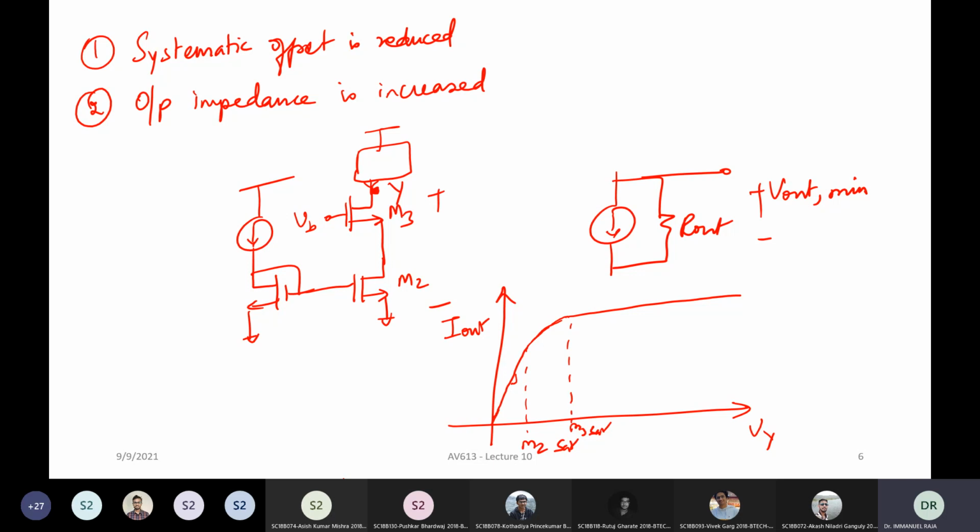And then you have your constant current source. Okay, and in order to prevent systematic mismatch, you actually need VDS1, which is equal to VGS1 here. So it's not just both being in saturation, right? After your M3 saturates also, there will be a little bit of, I mean, it's very difficult to see these things clearly as regions.